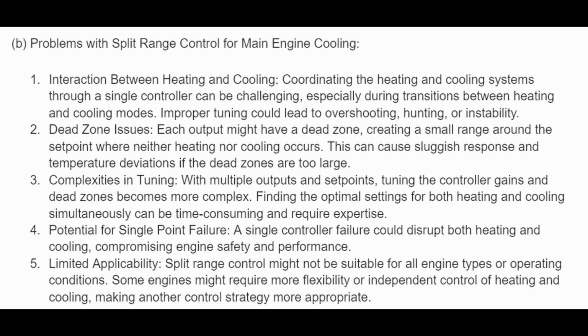2. Dead zone issues. Each output might have a dead zone, creating a small range around the set point where neither heating nor cooling occurs. This can cause sluggish response and temperature deviations if the dead zones are too large. 3. Complexities in tuning. With multiple outputs and set points, tuning the controller gains and dead zones becomes more complex. Finding the optimal settings for both heating and cooling simultaneously can be time-consuming and require expertise.